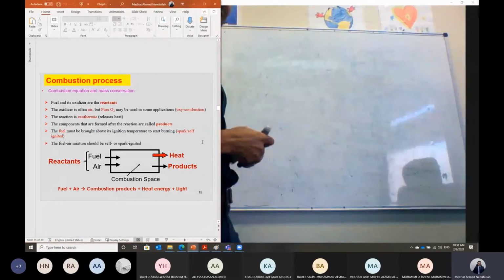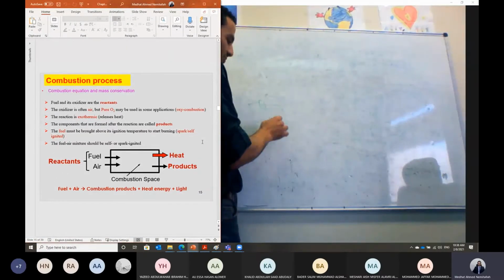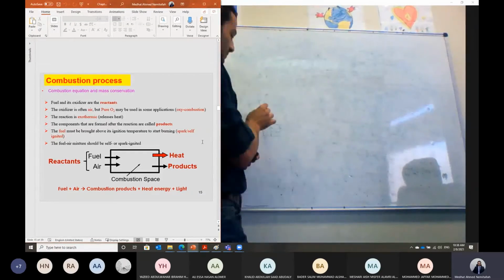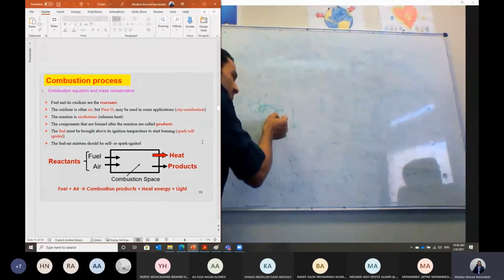Yes, because in a diesel engine, as you know, we inject the fuel by the end of the compression stroke. So the piston is going up in the second stroke, and we just inject the fuel. There is limited time for this fuel to mix with the air and to complete the combustion. This is during the end of the compression stroke and during the expansion stroke. So we have to provide more air in order to make sure that all of the fuel will have enough air. There is a problem of time. The fuel does not have time, unlike the case of gasoline. In gasoline, we inject it with the intake stroke, and it goes through the whole compression stroke, so they are mixed very well. But in a diesel engine, the time is limited.